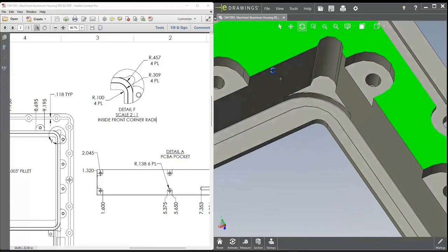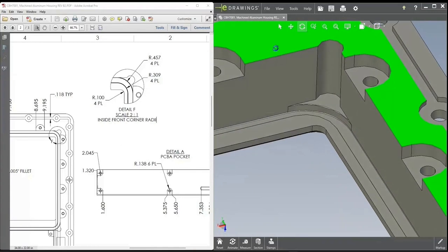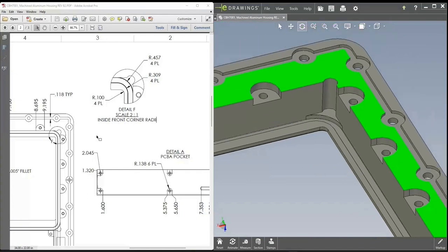So looking at this part, imagine that we have a tool coming down into this cavity. It's going to have to go in here and create this radius and create this channel, but we have this channel right next to this wall. So that's a challenge for us in order to get a tool that's that long, going to reach down in there and be able to still mill that channel. So when we go through all of these parts and all through these details, we have to consider, again, the best way to fabricate the part in the most efficient way to do it.